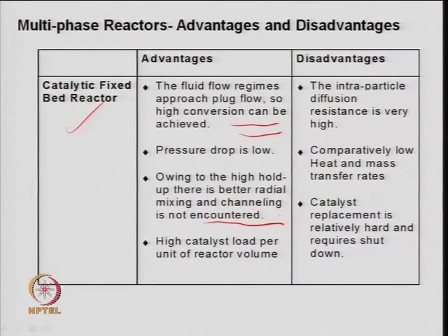So, this is what I was talking about in the case of a fixed bed reactor, when you compare it with a two phase system, right. When you have the liquid flow, what happens is the liquid bypasses the catalyst, it just comes from the side of the wall, right, or it comes from the void space between the particles. So, here you can have a better design, right, and flow conditions are different.